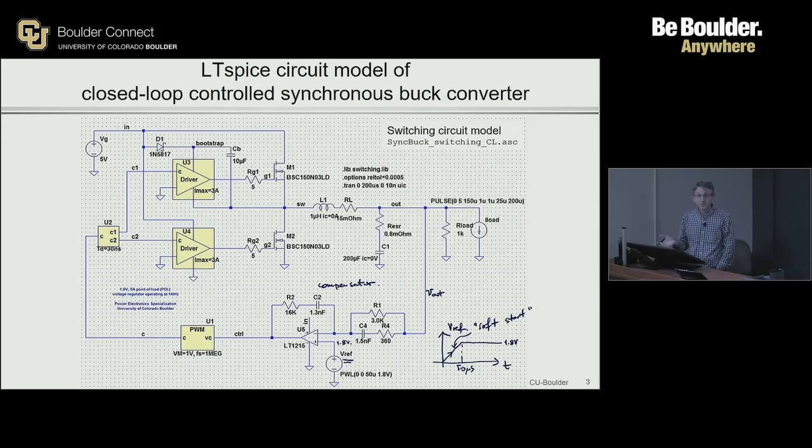What type of compensator do we have here? There is an integral action because of this. So this is your I type thing. On the input side, you have this parallel combination of R and the series combination of a capacitor and resistor. That's going to give us a 0 and a pole. So that's going to be a PD action right here. And overall, this is going to be a PID compensator.